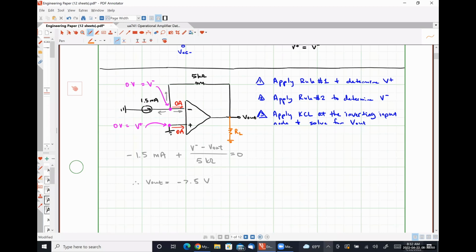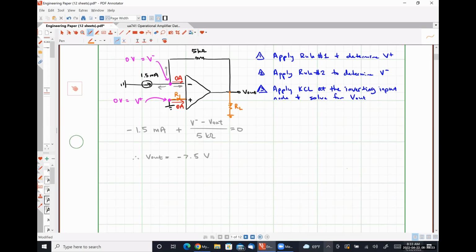What if we put in a resistor right here? I'm just going to call this guy R1. Between the non-inverting input terminal and ground. Would that influence the behavior of the circuit in any way, shape, or form? No, because we know that no current can flow through it, and therefore no voltage drop occurs over it. Okay. All right, good job. You guys are picking up on things quickly. That's wonderful.